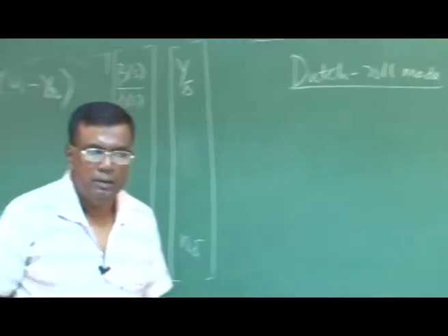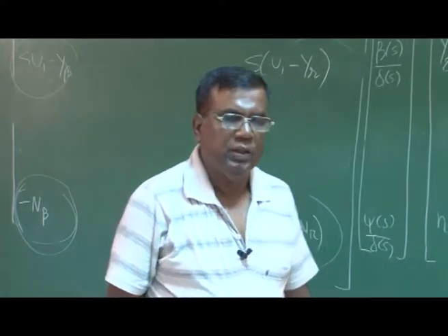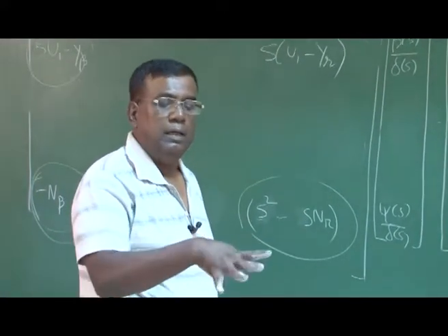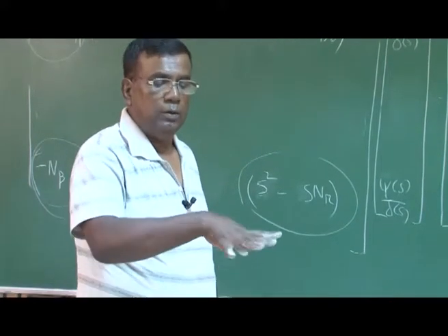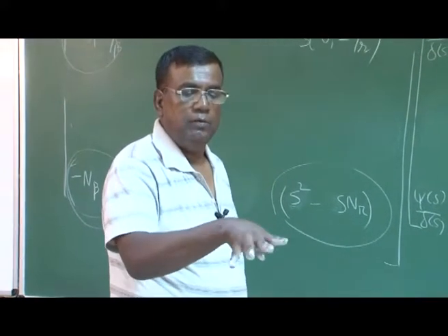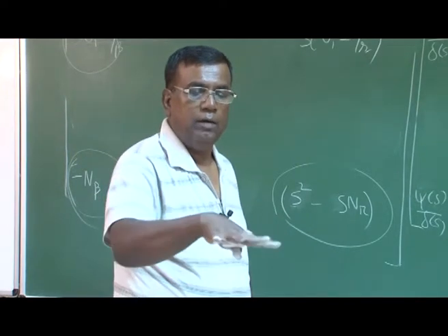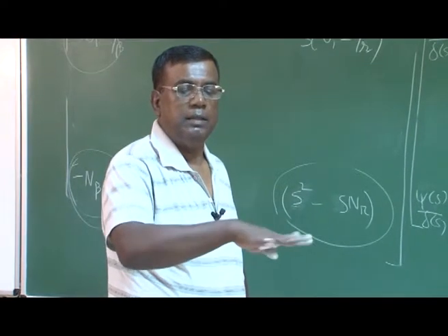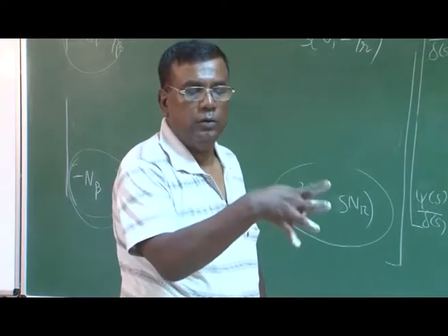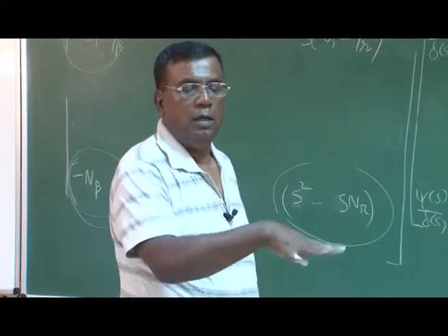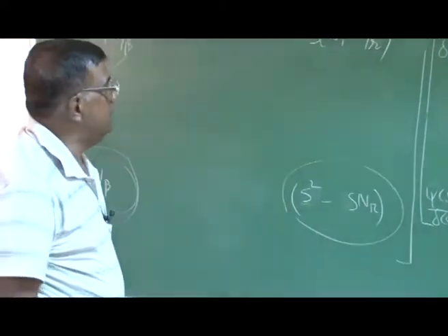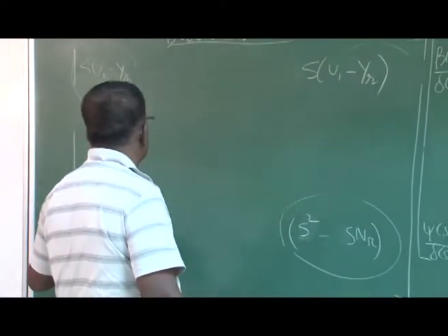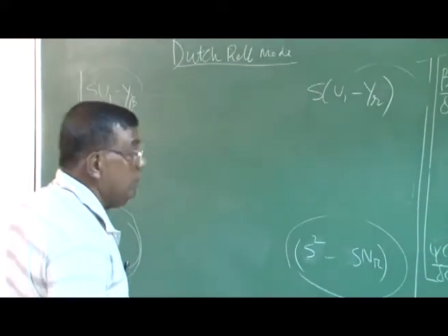Physically, what is it? As we have agreed, the airplane in the lateral directional case can get excited into spiral, roll and Dutch roll. Dutch roll is primarily yawing like this, and also this motion, right? Although there will be some bank disturbances, primarily it is this and this. This is the Dutch roll. So you go like this. And this is approximated by keeping only this fourth term, with beta and psi, no psi dot.